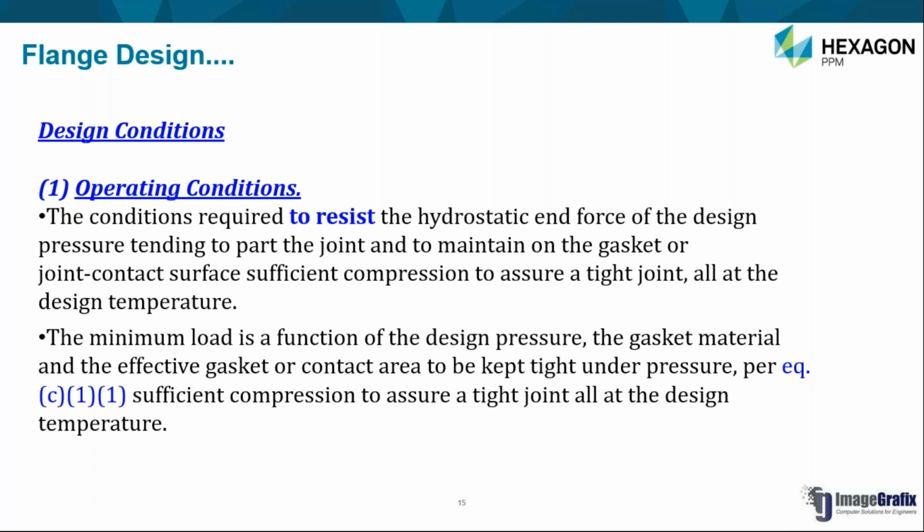As for a gasket, there are two factors. One is called the M factor and the other is called the Y factor. The M factor is the maintenance factor, and Y is the gasket seating stress factor. For every gasket, due to the property of the gasket, whenever the gasket is initially compressed during its gasket seating condition and then pressure is given to that vessel or equipment, the tendency of the gasket is to relieve some of the compression.